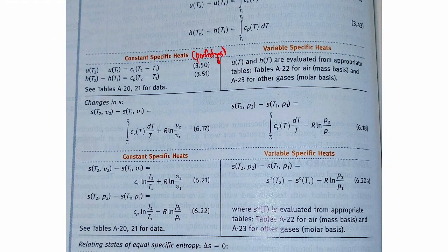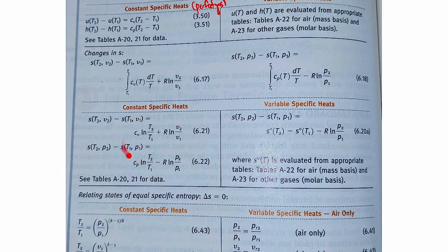What happens if you assume that you're dealing with a perfect gas, and how you calculate changes in specific entropy for constant specific heats or variable specific heats. By the way, just for the variable specific heat, so this is the ideal gas, the difference in specific entropies is not s° minus s°, right? This s° value, this is not specific entropy. What I'm highlighting here, that is not the difference in specific entropy.